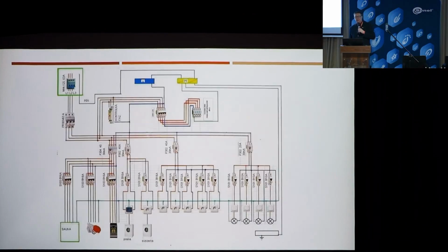What does that give us? Well, if we look at an example electrical installation, this one happens to be a switchboard diagram, and the circuits coming out of it. It's very easy to prepare an installation like this for measurement. After switching off the residual current device, unfortunately, with one pointer, you can't show everything on all the screens at once. Then, after switching off the protection, we can safely measure that circuit.